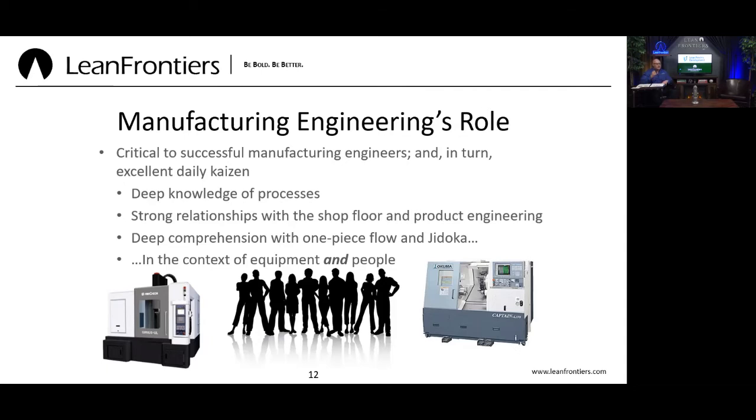So that means our fixture design became important. If you're familiar with chaku, that concept became important. Physical safety protocols around the machine became important. One-touch start, so we had to meet safety standards. All those things became important for us to allow a more stable line for the operator, because we wanted any operator, anytime, to be able to load and unload a machine within at least 5 seconds, repeatedly. So it had to be comfortable.